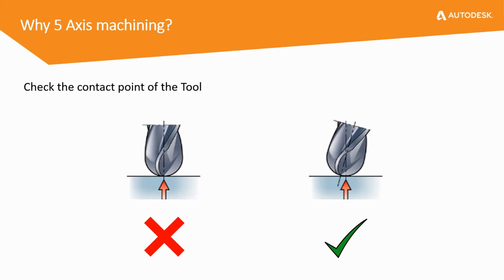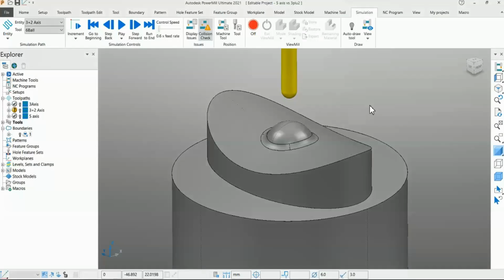The second disadvantage in using this tool perpendicular to a surface is that most of the 4-flute tools have only 2 flutes at the edge of the central portion. The final one, the use perpendicular to a surface decreases considerably the duration of tool life. So it is necessary to tilt the tool axis to avoid machining perpendicular to a surface. So for better understanding of 5-axis simultaneous toolpath, let us have a closer look between 3 types of toolpath.